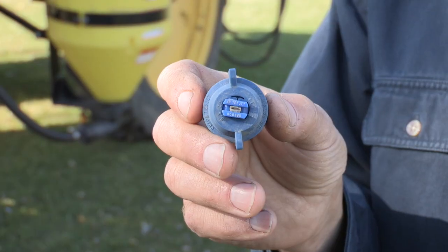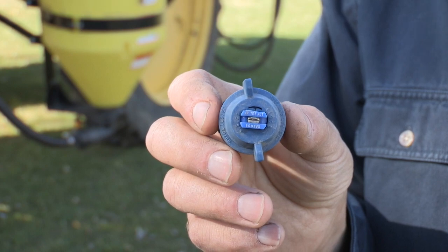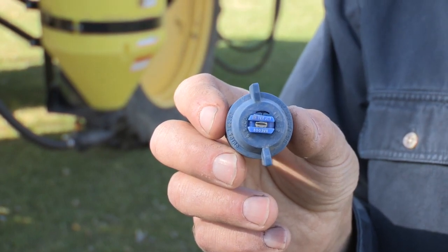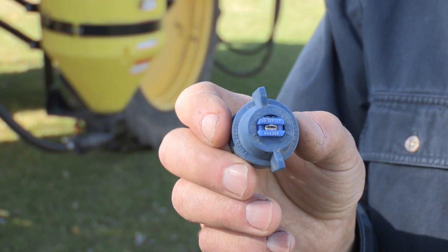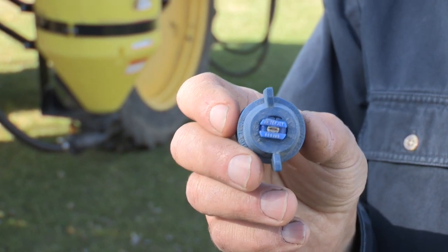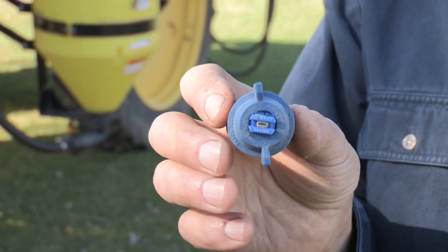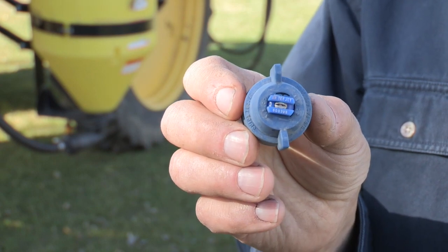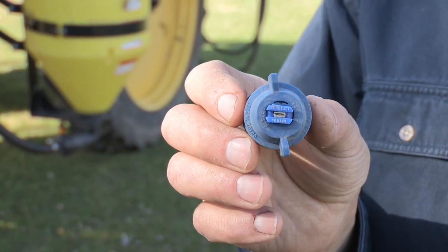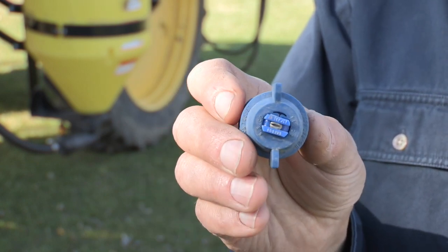The sprayer that we're going to be calibrating today happens to have T-Jet XR 8003 VS nozzles on it. And the important thing to note about these is the XR stands for extended range, meaning that it'll maintain a pattern over a wide pressure range. And the 80 designates that this is an 80-degree nozzle, 80 degrees of pattern from the nozzle tip.